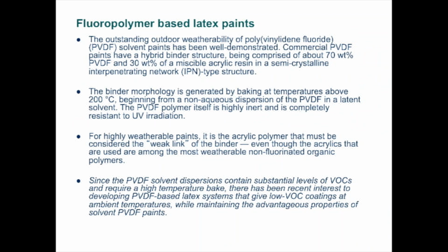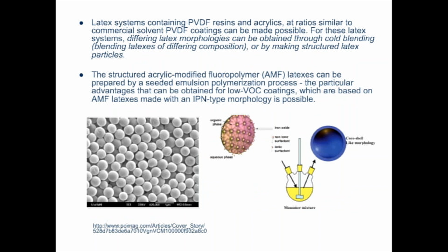Fluoropolymer-based latex paints are actually dispersions of materials like PVDF, surfactants, and other resins that can produce a formulation where you can first coat them on a surface and then bake them, or high temperature curing provides the final process to give you a good finish and protective function. Okay. So again, PVDF is a more expensive coating material, but very effective when combined with latex ingredients or binders.